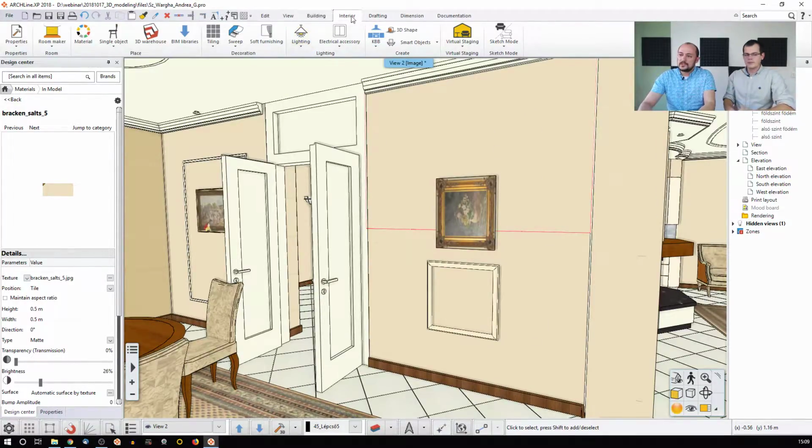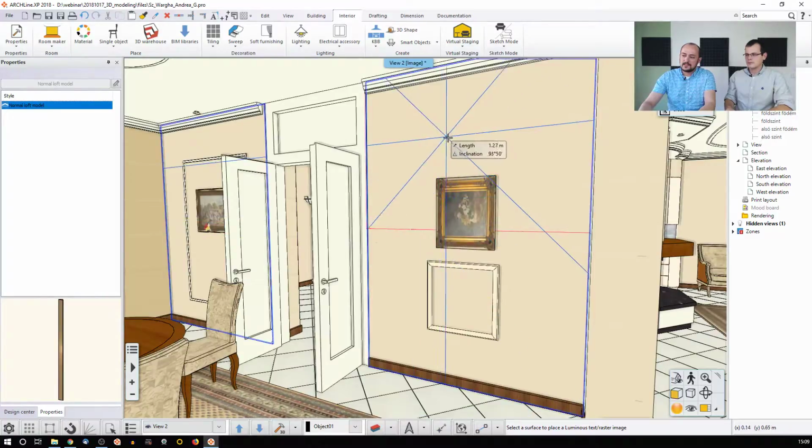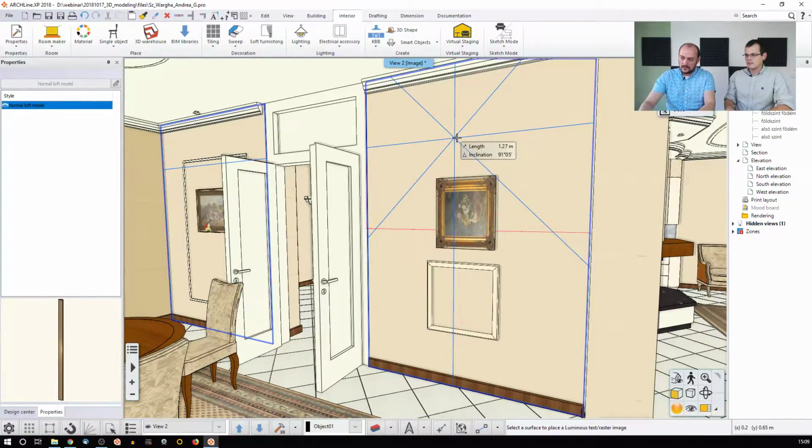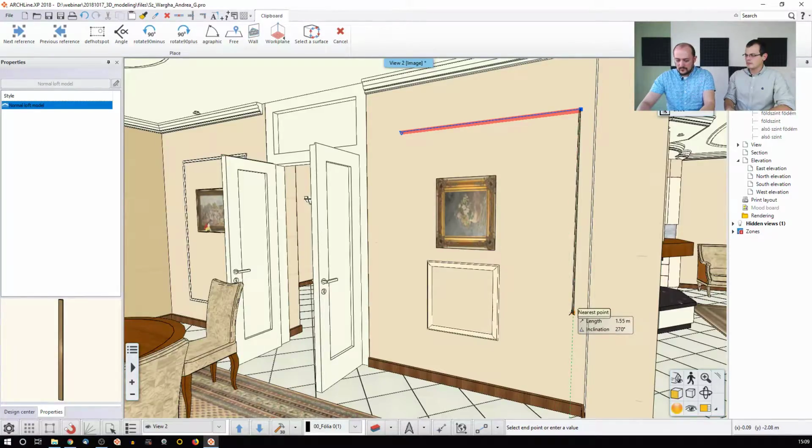You just use this interior sweep tool, sweep, and then you need to click on a surface, telling the software that this is the area where I would like to work now, and just click there. And then you just literally draw. You just start. I'm using the same values. I'm clicking here and saying, okay, this direction, this should be, I think it was 1.5. And this direction, this should be 2. And this direction, again, 1.5. And again, let's close it back on 2.